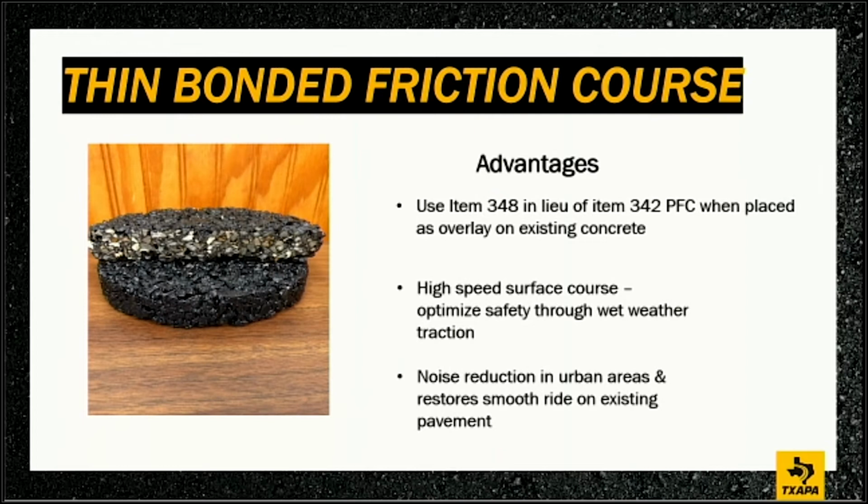We have the advantages, again, you can place it on concrete, utilizing that high polymer membrane. It's a high-speed surface course. It's great for wet weather traction, and it reduces the noise. In urban areas, we've been known to not have to put such high sound walls up when we utilize PFCs and thin bonded wearing course. That's a big deal as Texas continues to grow. It sure is.